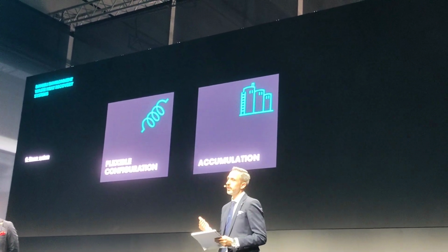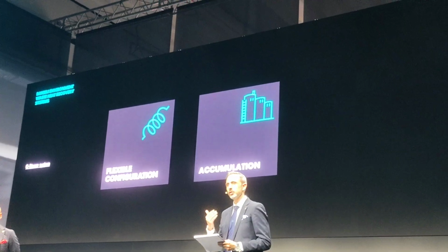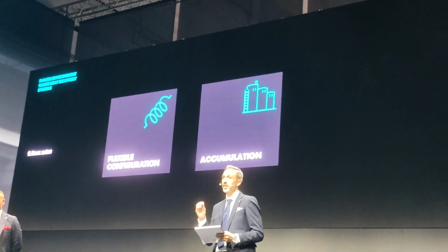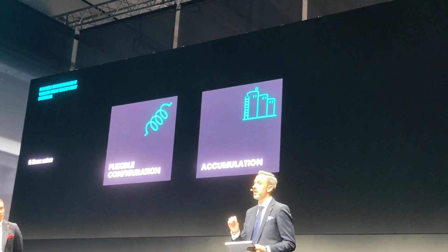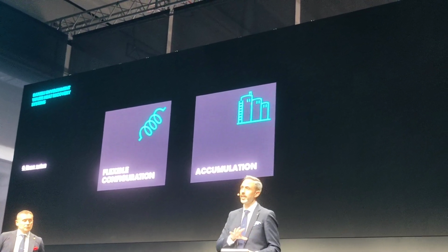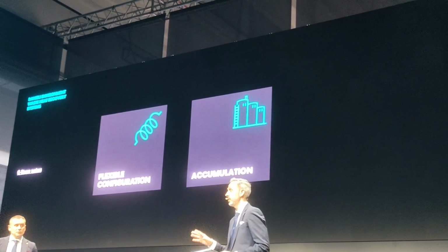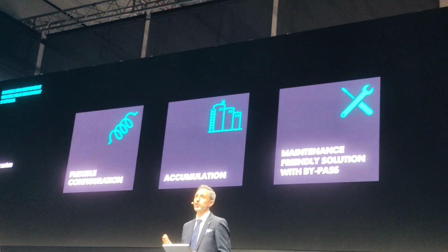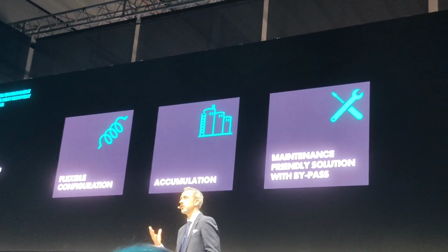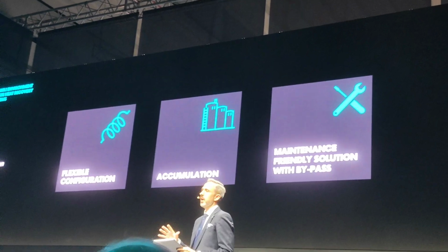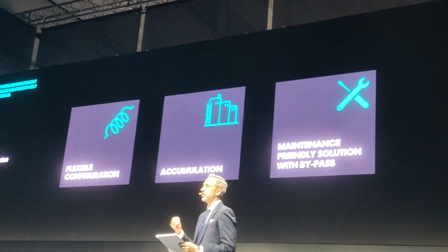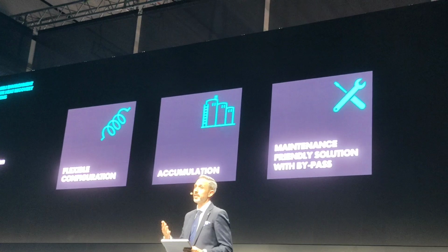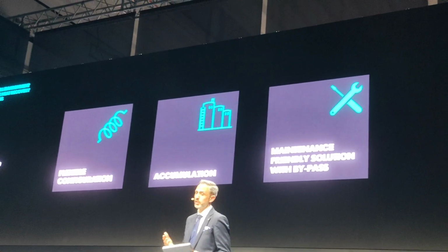They are both designed to mitigate the discontinuous process of the electric arc furnace, thanks to their accumulation system, the steam accumulator in one case and the hot water accumulator in the other case. And they are both maintenance-friendly solutions because the activities to be done on these systems are basically just regular controls and the standard periodical maintenance to be done during the scheduled shutdown.